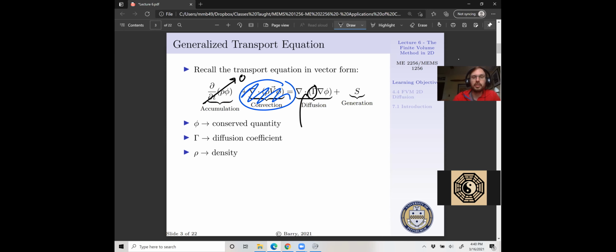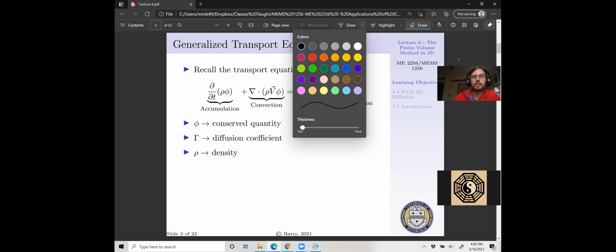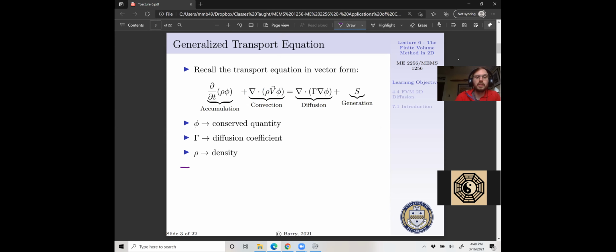Now, for you guys that are pretty savvy with heat transfer, this would be the same as the steady state conduction equation. So you can recall you'd have the divergence of lambda or kappa grad T, right? And you'd set this equal to 0. Now the divergence of lambda times the gradient of T, T is a scalar quantity, right? So you'd have the divergence of this, and let's just write it out in the full form.